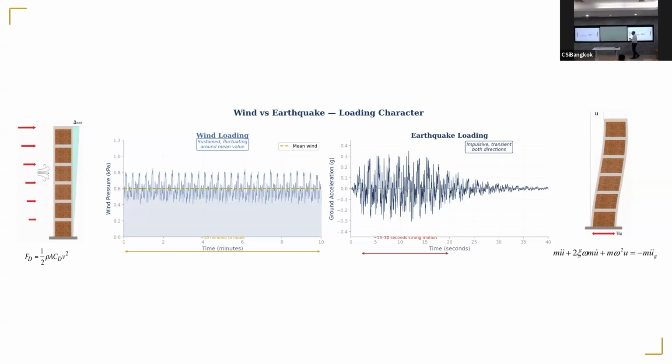Second thing is that the earthquake may last maybe 45 seconds or something, but a wind storm can last an hour or more. So the time history is very long, which means the analysis will take a long time to run. And also there will not be just one, there'll be several wind time histories on the structure at the same time. So people normally don't do that because it's so complicated and so difficult to do. So the codes will take the mean. It reminds you of the equivalent static force from the earthquake. So they take that and apply it as a pressure on this one. So that's the basic concept.